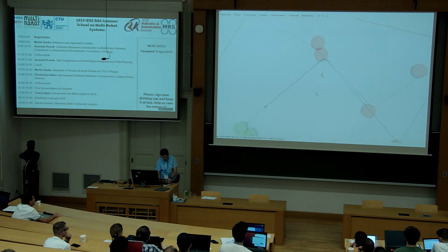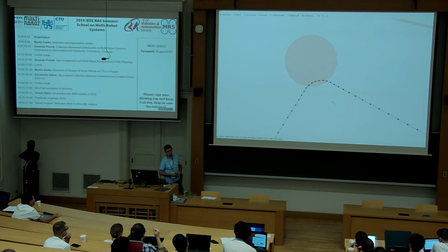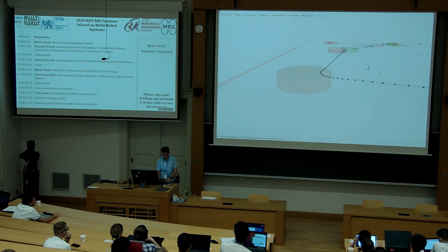Imagine when I look at this neighborhood, imagine then the drone's controller isn't perfect and it might cut the corner. Then the neighborhood will not be visited. It's then up to you how much of a slack you give the drone, how much of a reserve you will have in this particular situation. Again, one parameter in the code.